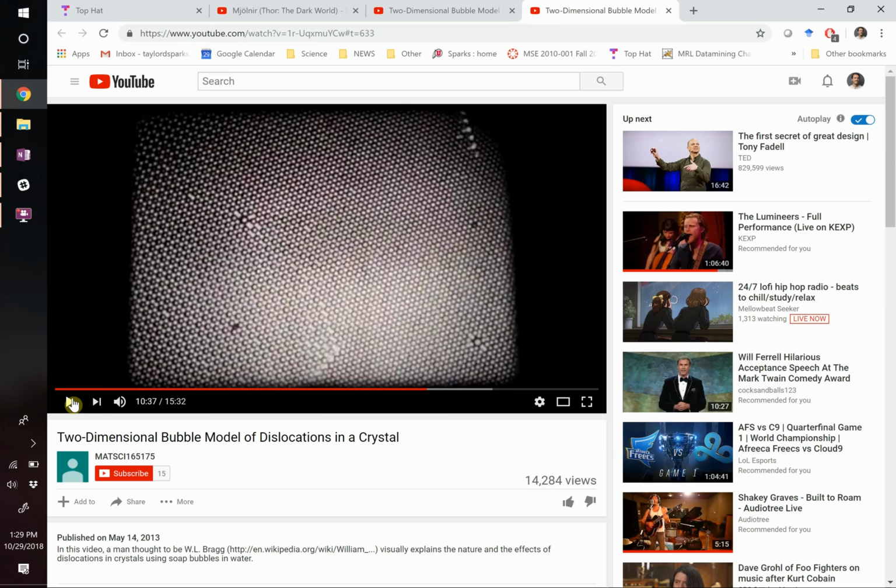Because these dislocations can move. You saw that you can slide them around as you apply stress to this material. If it goes zooming by that spot, what might happen? Any thoughts? I would assume it's going to interact, but I'm not quite sure. Let me ask you this. If it has a compressive region, do you think it will interact with the tensile region of your dislocation? Attractively, right? It's probably going to be attracted to it. So let's see what happens.